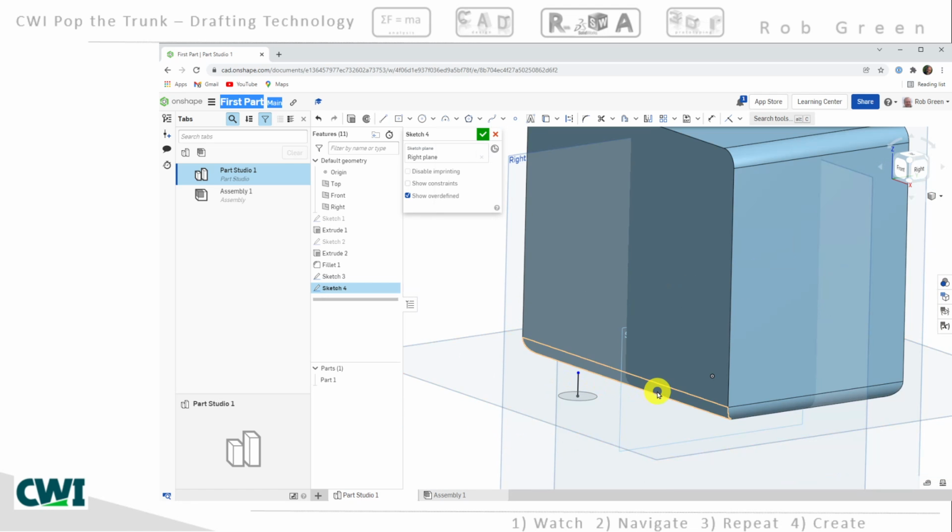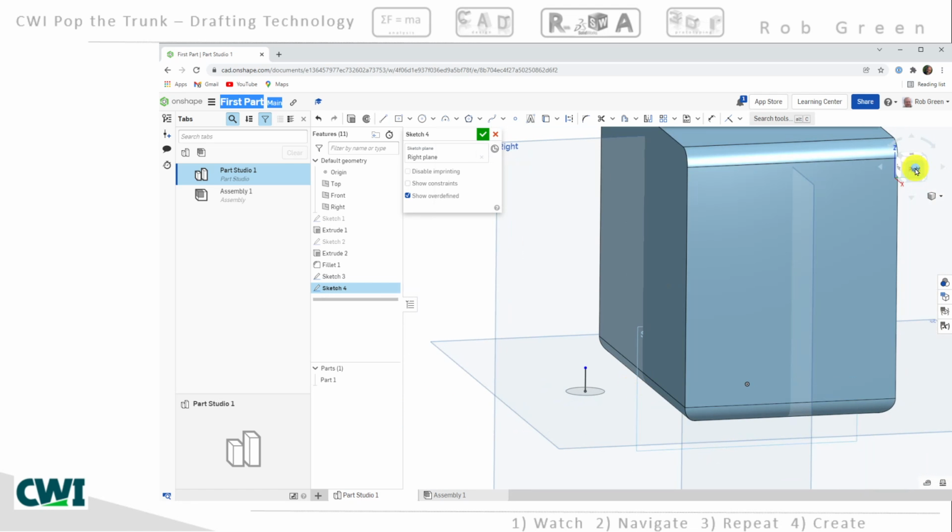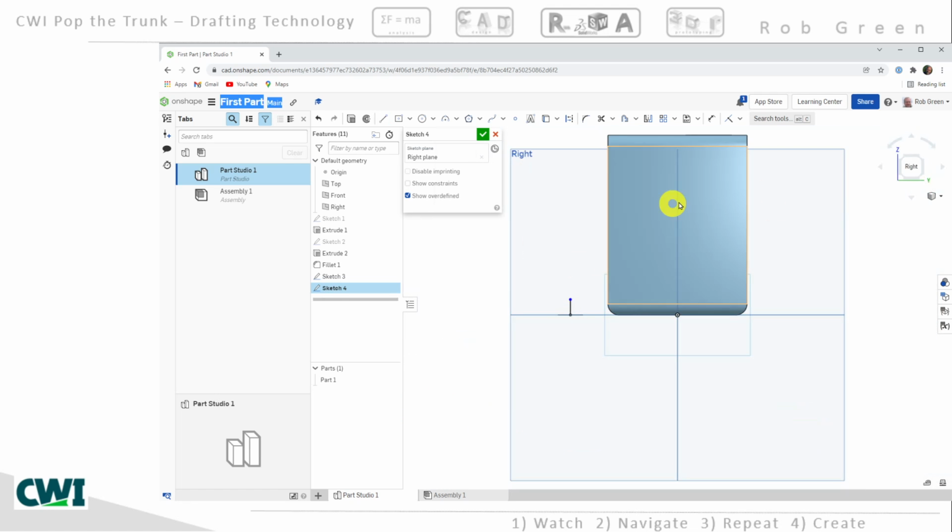And now I'm actually going to rotate and use the right face of my view cube. So I'm looking straight onto the right plane that I'm drawing on. And I'm going to choose to draw an arc called this tangent arc. So I want to choose this option. Choose it, come down to the end of the line that we drew, click at that point and begin to move your cursor up.